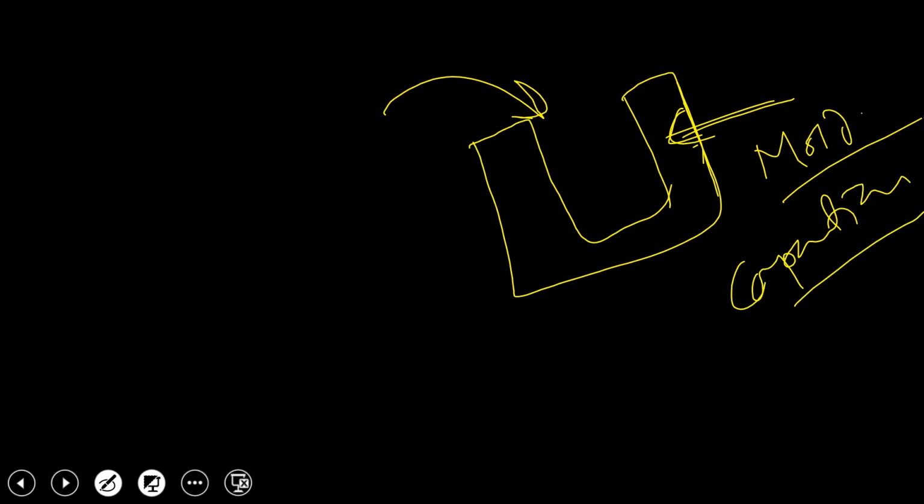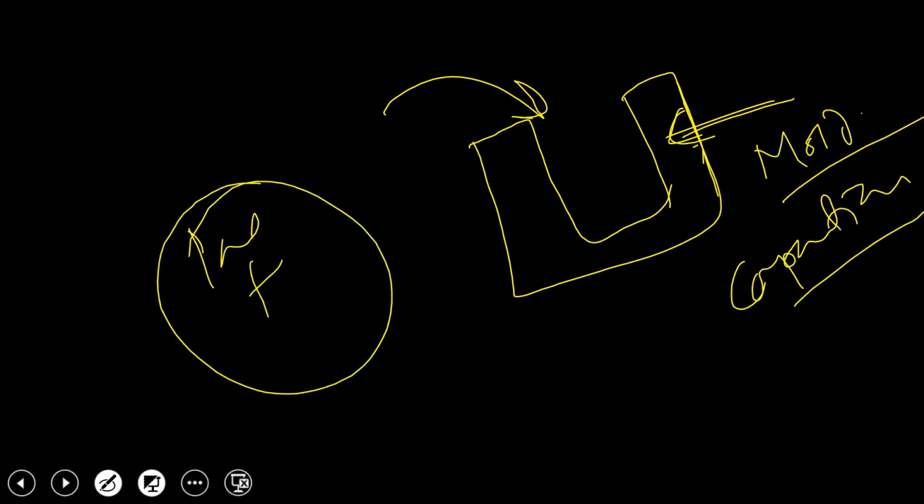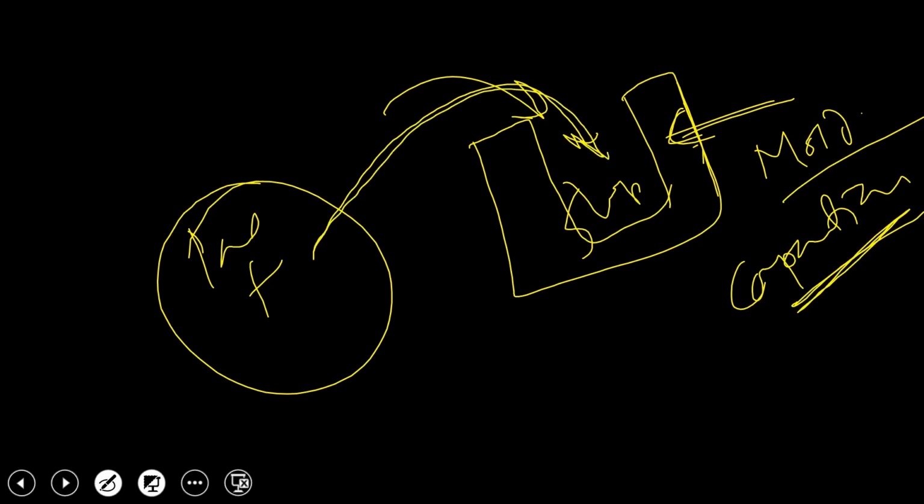When you took metal powders and added additives, lubricants and all, and you convert that mixture into the shape of the product, that process is nothing but compaction. So when you transfer this mixture into the mold to offer the shape, these lubricating or flow properties come into the picture.